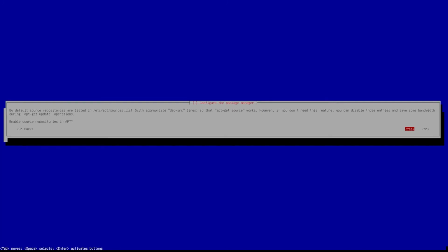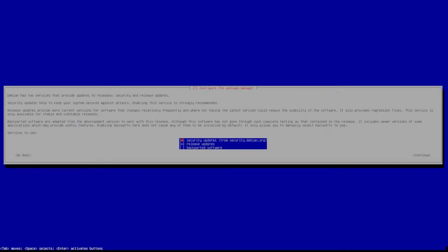You don't have to. This is just probably a bad habit that I've gotten into over the years, but after having had to fix computers 2 years after they were installed, 3 years, 5 years, sometimes 10 years, I find that having things like that turned on tend to be a lot more helpful than if they're turned off. You'll see in the next step when it asks to install the backports or not, that I will definitely select yes, backported software. I'd also recommend updating your Linux machines for Linux CNC pretty regularly, because if you let them get 2 or 3 years behind, it might be a problem. Not just from a security standpoint, but from a things change standpoint, and then might not necessarily have the stuff that you need to fix your issue, your compatibility problem.